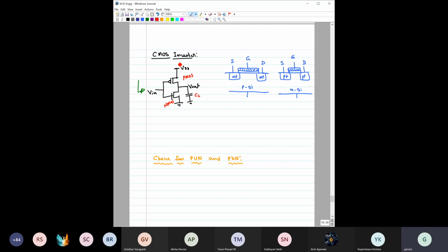So far so good. So here, this is drain, this is source, this is gate, right? For this transistor, this is gate. So what would be this terminal, source or drain? For PMOS, yes, it is source, it is drain. So it is source, it is drain. So the same current ID has to flow through both these transistors, right? I am saying the DC current, obviously. The DC current has to flow through both the transistors, if there is any.